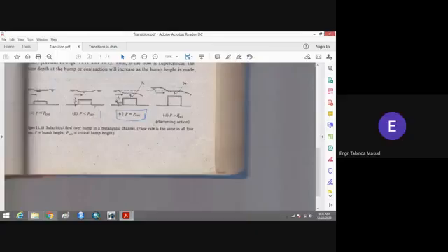This is what we were discussing, that in case of a weir across the channel, we may or we may not have the critical depth of the flow. You can see that this is a weir on a channel, this is a weir on the channel, but in both of these cases there is no critical depth over the weir. However, in this case we have the critical depth of flow over the weir. In this situation, you can see that